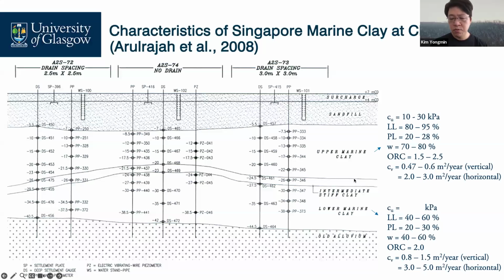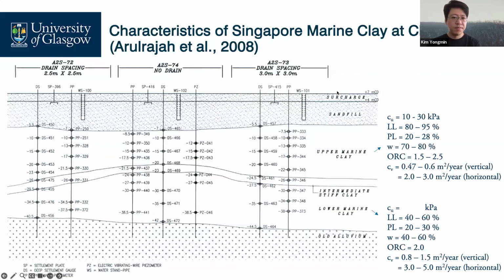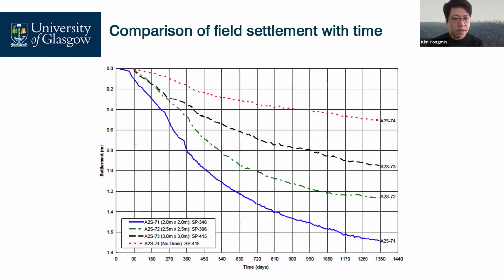Prof, how do you know? We have settlement markers here, here, here. And then your total station constantly measures the heights. You run this, right? Then the x-axis is time, the y-axis is settlement.